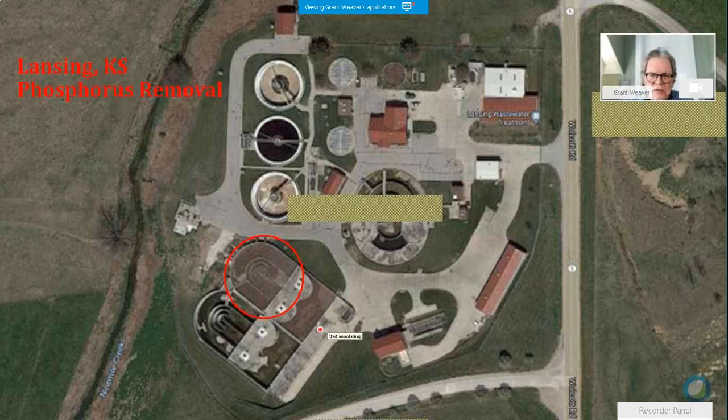So in the anaerobic zone, I like to see a minus 200 or more negative. The more negative you get, the stronger the septic conditions, which means the greater the possibility of odors. So depending upon the chemistry of your wastewater and how near neighbors are to you, is how much you can drive that into a negative. So if you're not getting minus 200 or thereabouts, you probably need to make this zone more anaerobic.